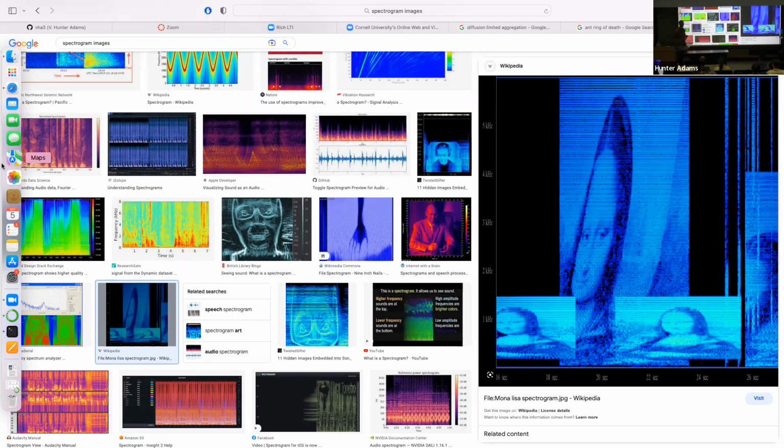And there's also some morphing of that sound as a consequence of passing over your head and ears and so on. And you can develop a function that approximates that so that you could generate a synthesizer and then implement one of these head transfer functions so that you're sending slightly different sounds to the left and right channels of the DAC, each of which goes to a different earbud. You put it in the earbuds and make it sound like there's a fly flying around your head.